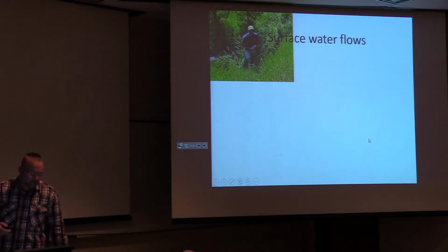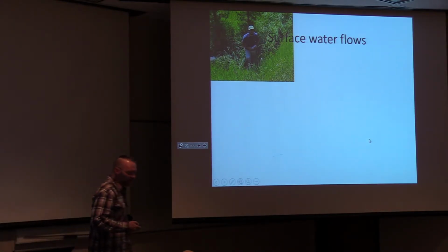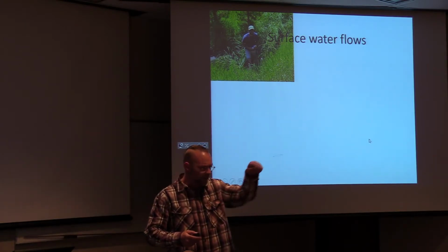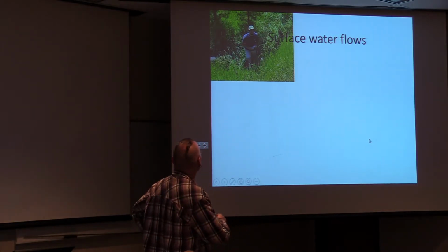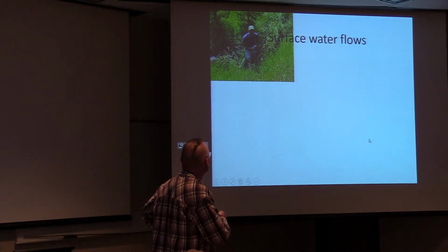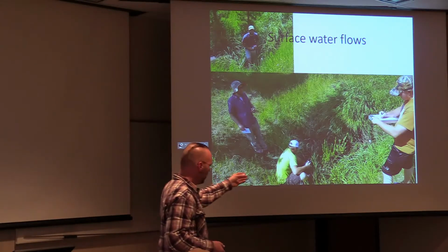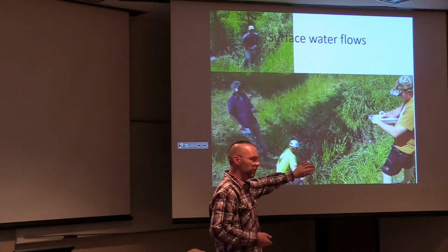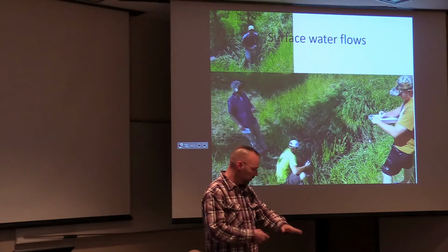With surface water flows, there's John. This is our hydro field camp. We went out and we did a bunch of surface water flows in August. Evan's been out there targeting a few sites, and we did a bunch of sites trying to do a surface water balance where he injects a high concentration of saline water and then a student measures the salt go through.